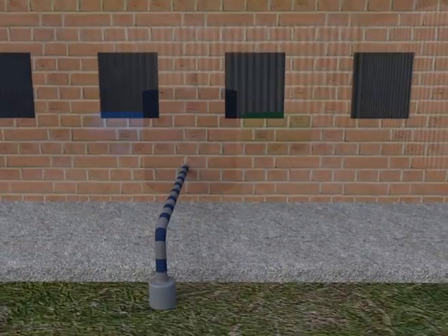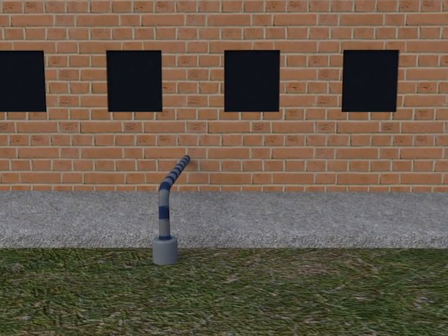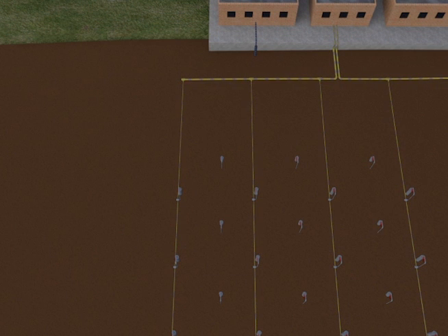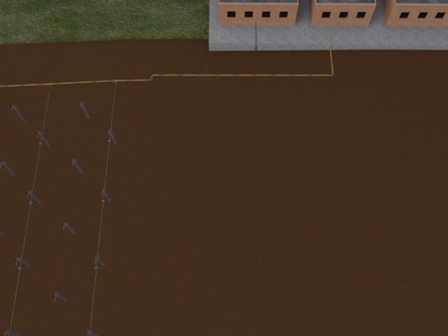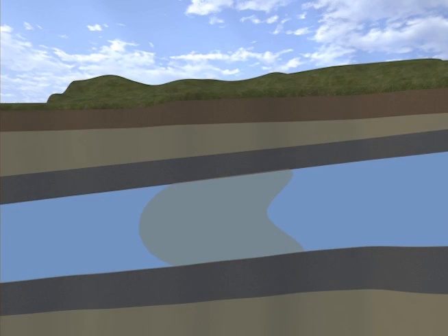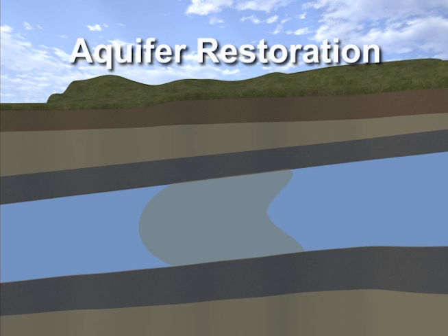The production cycle continues until the production fluid from each extraction well no longer contains economic quantities of uranium. At that point, the active in situ leaching operations are moved to another part of the ore deposit. When the ore deposit has been mined out, aquifer restoration begins. Aquifer restoration is the process of returning the water quality within the production or mine zone to target restoration goals set by the Nuclear Regulatory Commission.